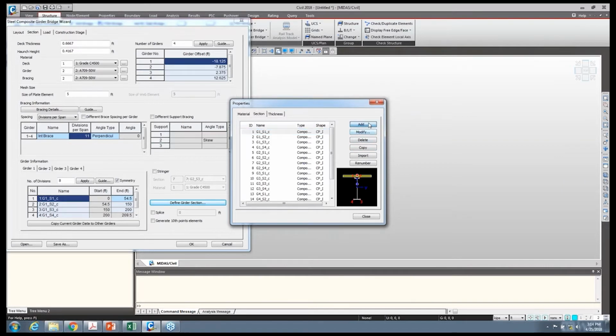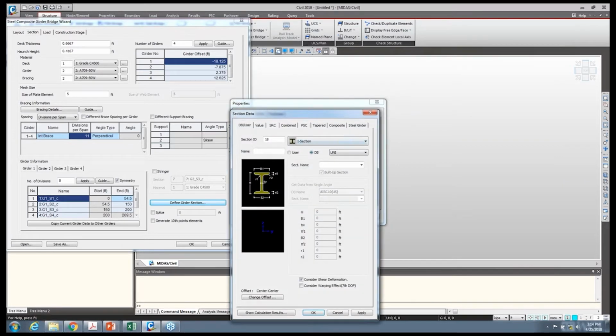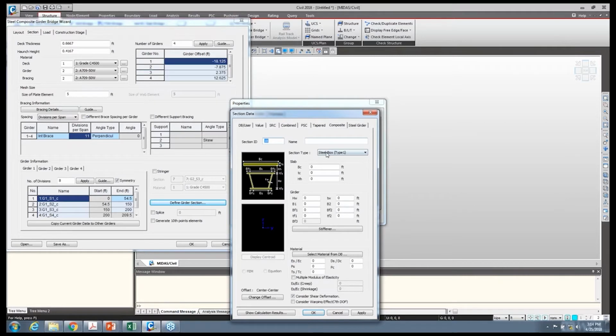When I brought in my girder sections, I don't know if you saw this earlier, but this was actually blank. The reason why I removed those particular items from the import, which you saw earlier, is so I could have my first section property have a number 1 designation. And so this automatically populated for each one of my girders. This is just kind of a trick that you learn over time, so you don't have to do a search through a number of large libraries of section properties.